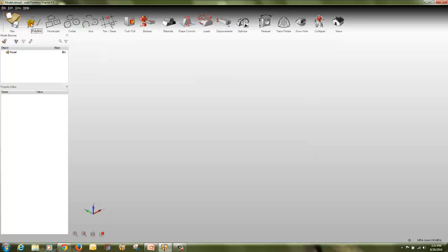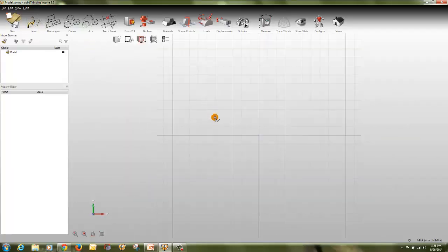Now the polyline, which is the continuous line. You can have a continuous closed loop with this. You can also change the distance of any one line, like say if I want 75, this will be a bit smaller. If I right click, I can again change the dimension. One more shape I will show you. So I can change the shape as I want.